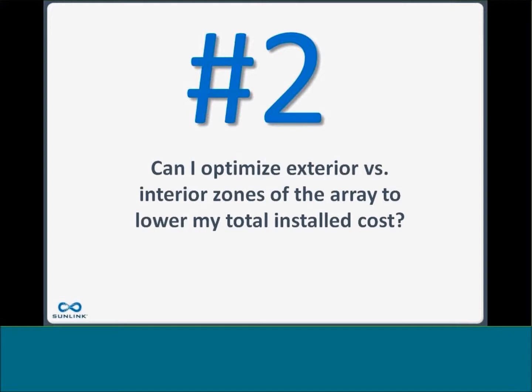Another question here: what type of soil is most difficult? Various soils are challenging for different reasons. When you're looking at your axial capacity of your post, sandy soil is often the most challenging. It doesn't provide as much axial capacity as some other soils, and so that is where you're usually seeing that increased post spacing really affecting how long your foundations would be in sandy soil. And then other soils can be more or less challenging for other reasons.